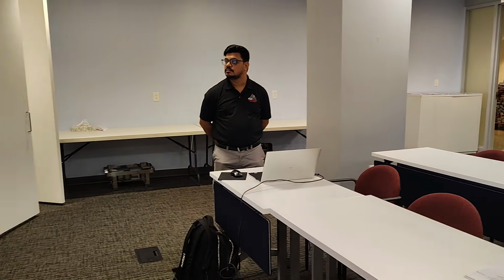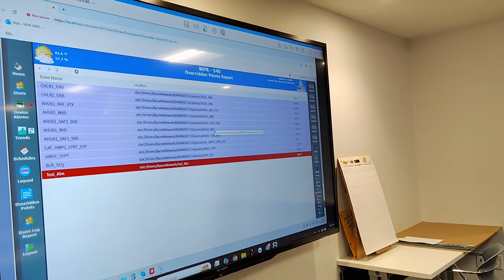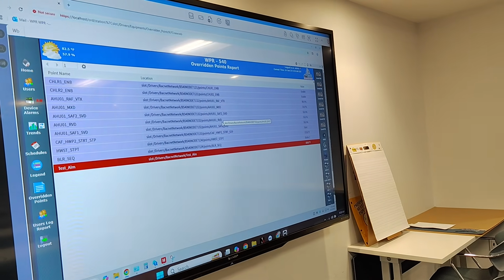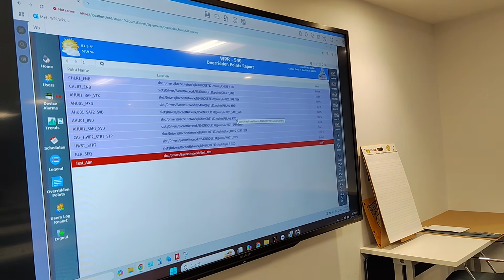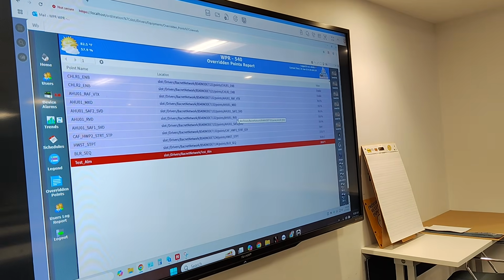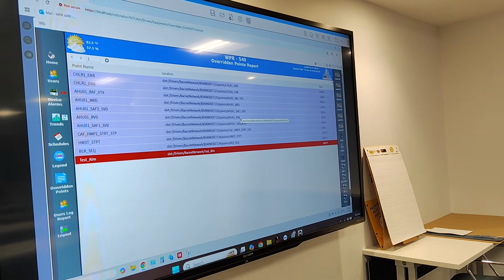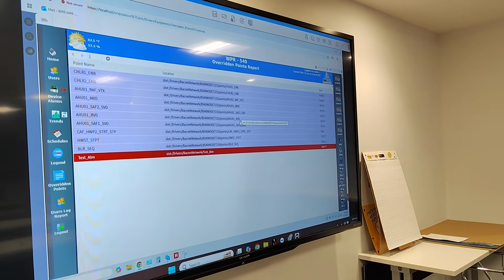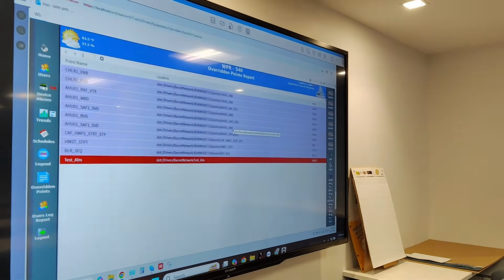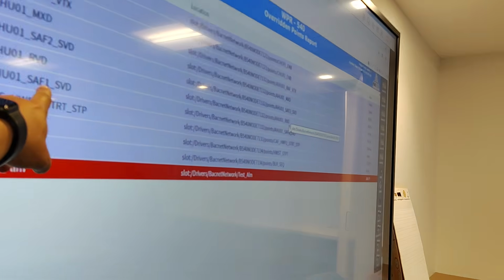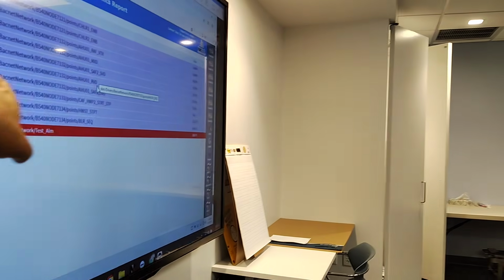Where it says enabled, it's enabled, but what about the 10%, 50%? Enabled means that it is overridden to the on state. That's the value of the point. Binary points are going to show up as disable or enable, and analog values will show up as whatever their frame of reference is. If it's a percentage, it'll be 0 to 100. If it's a voltage, it'll be whatever that voltage is reading. So that is the overridden value. This means in AHU01, he made the supply air fan 50% today. Yeah, 50%.